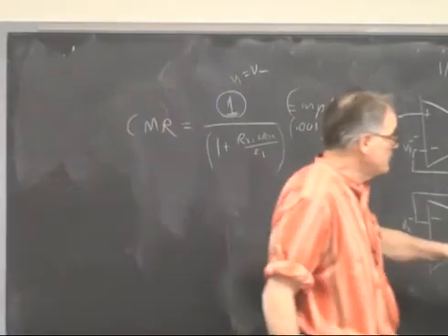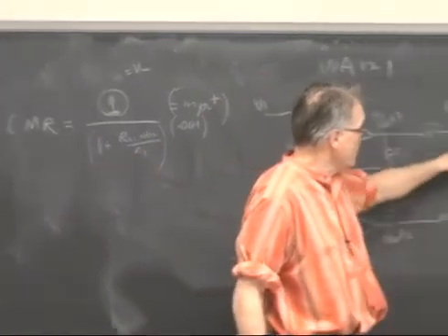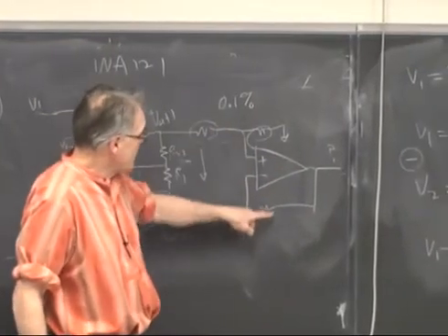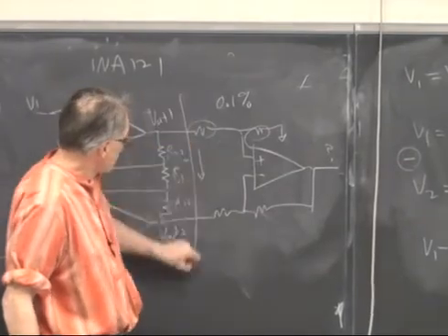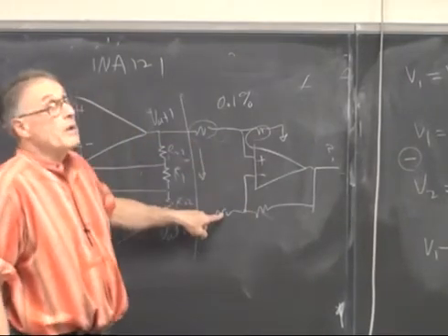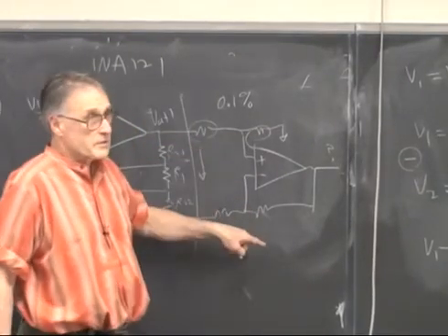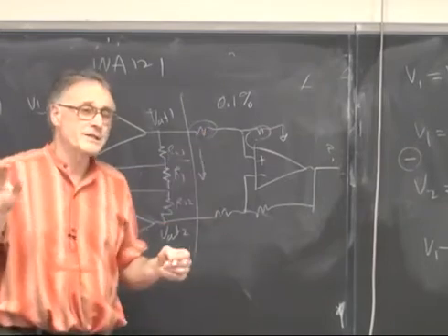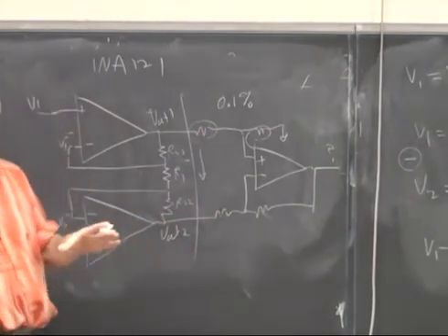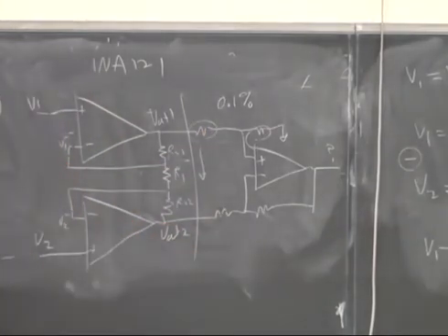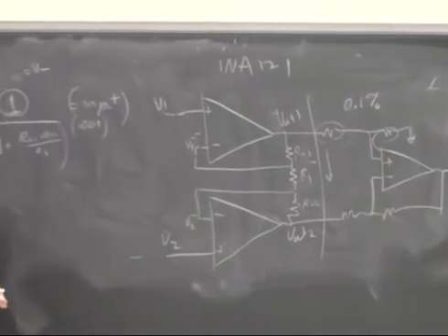The common mode gain for this stage depends on the matching of these four resistors, but because they're completely inside the package on the same substrate, they can be laser matched, laser burned to the right resistance, and are quite stable.